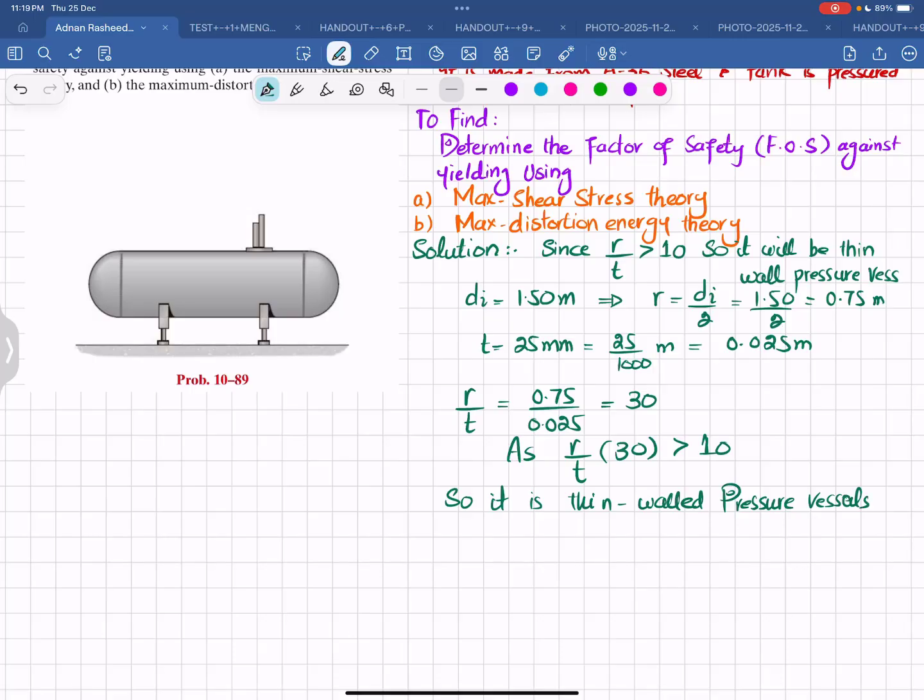And we know that the formula for a thin wall pressure vessel is, we have hoop stress, which is sigma h, and that sigma h is the maximum stress. We can also say this is one of the principal stresses. The formula is PR divided by t.